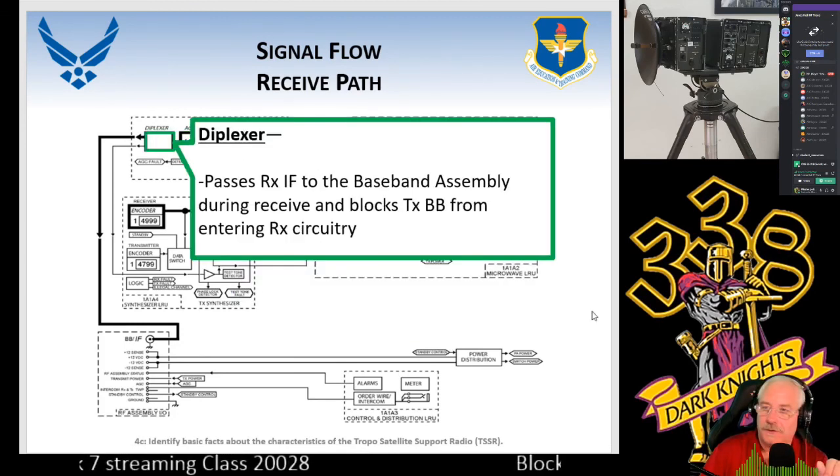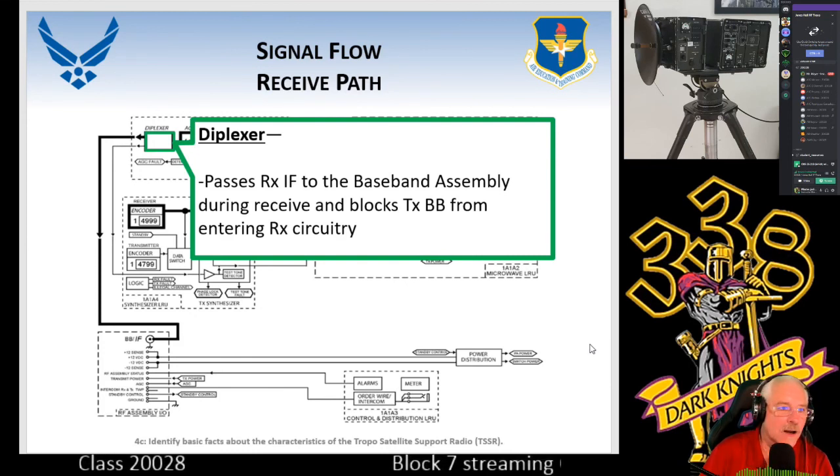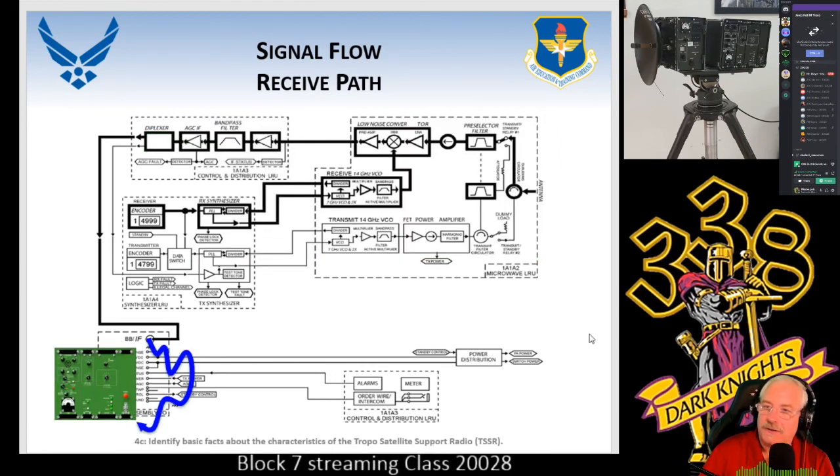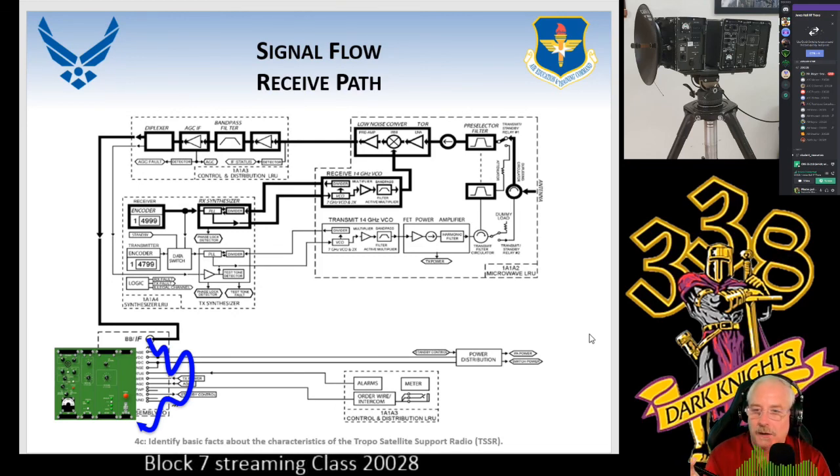We're going to run it through a diplexer. Again, it's going to keep the 70 megahertz from getting down on the transmit line, but it's going to let it go out the back of the baseband line. We're going to prevent the baseband from getting on our receive line. I know it's a lot of information on that. Picture the diplexers, okay? One on the RF assembly, one on the baseband assembly. You got an input and output as well as an output input on one device.